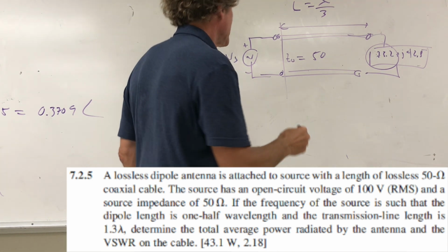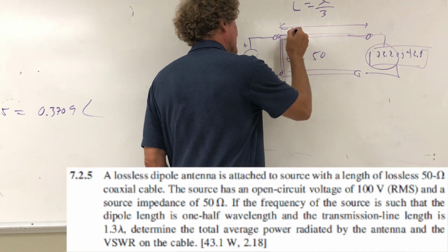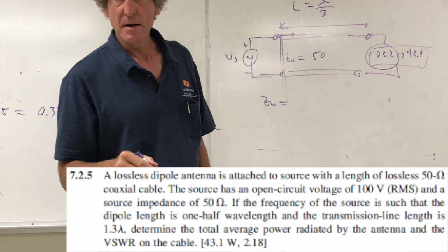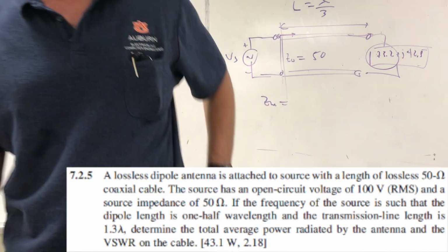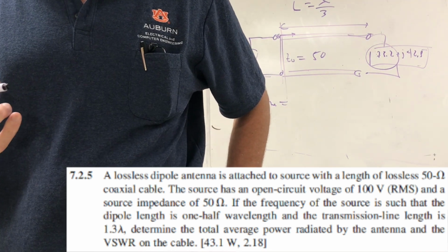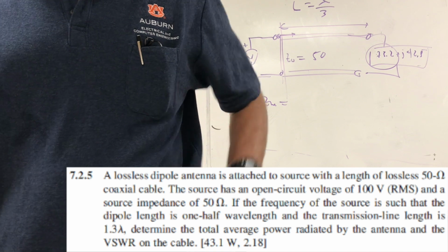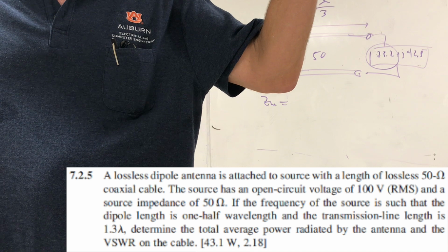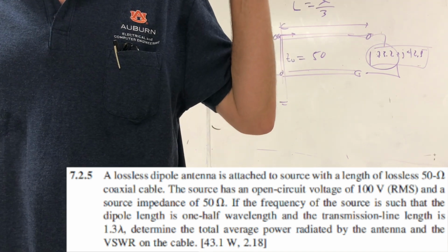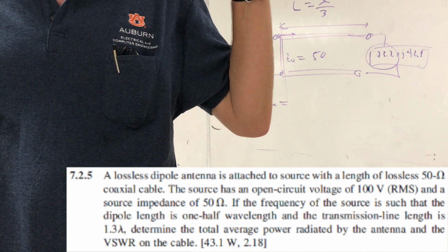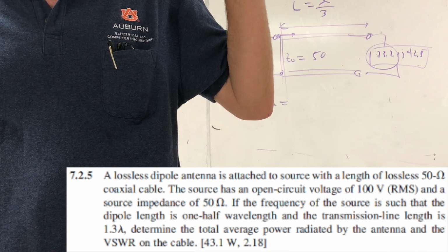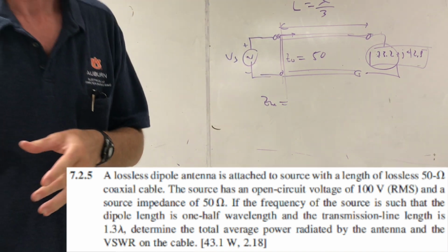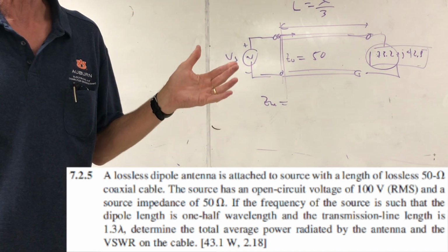Now, what do you know about Zin here? It's 1.3 lambda. Zin is equal to, what did you say? 1.3 lambda. Does it matter if it's 1.3 or 0.3, class? I'm getting at something. You remember how every time you go a half wavelength on a transmission line, you can basically remove that segment if you're just looking for the input impedance, current, anything like that. You all with me? Every half wavelength, everything repeats itself. If it's 1.3, get rid of the 1. It doesn't matter, just 0.3.